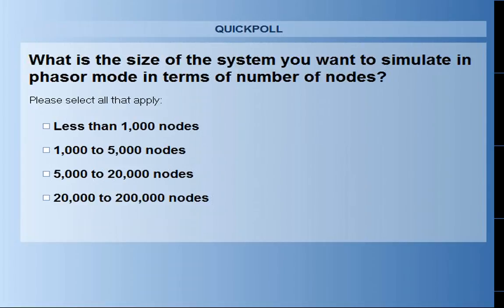In this demo, I have used the RTDMS tools from EPG Corporation, and I am using the same network from Hydro-Quebec. I assume that I will have 10 PMUs in different locations in the province. I gather the data and send them to the visualization client.